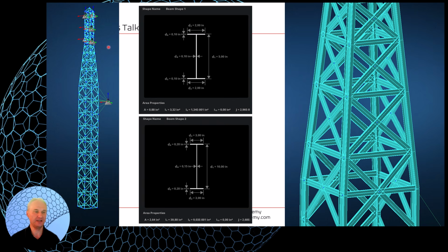And here you see the lumped masses, different lumped masses attached using MPC elements to the tower, as I told you, because the total mass of the system is really important to capture properly. So the mass of those antennas here are properly captured.